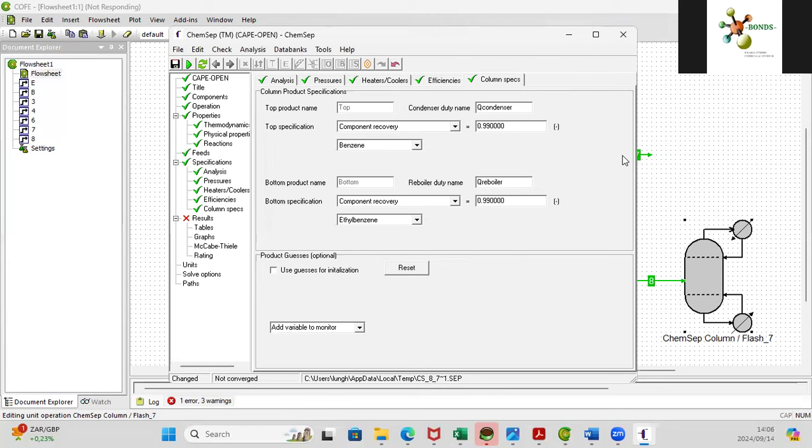And then we will bring it back down so that, if the column is too big or too expensive, what you usually do when you're doing your equipment design is go back to your process specifications in order to make it cheaper. So in other words, if you are recovering 100%, and you reduce your recovery to 96%, your column may be smaller because of requiring fewer stages.